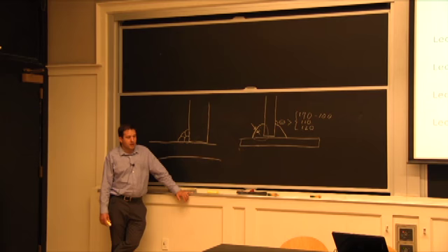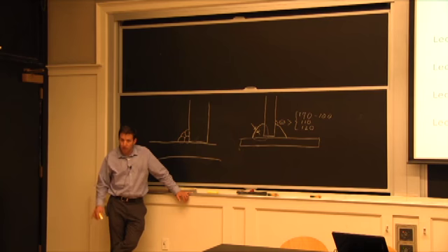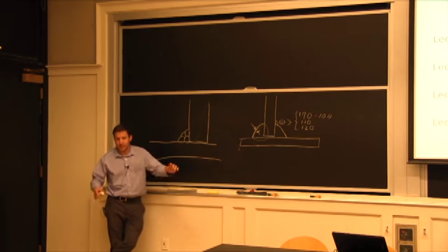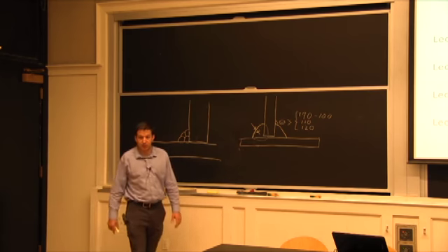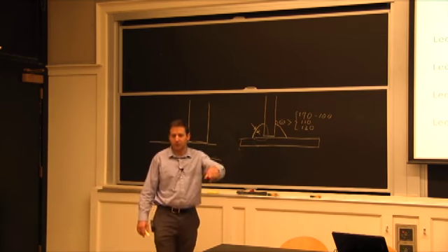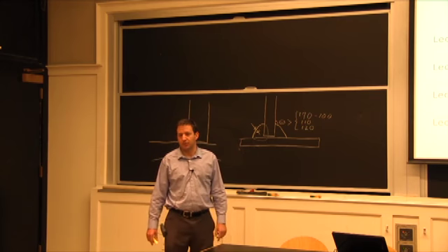So qualification, I think, is just part of the specification, and when I was talking, for example, yesterday about the ATV, whether it's okay to have welds that are not good all around, that comes into qualification testing. You hope that in qualification they do it all well, and then you may say, well, because I'm using some robots and the setup may vary a little bit every once in a while, maybe I have a weld out of the 4 all around that's not going to be fully fused.